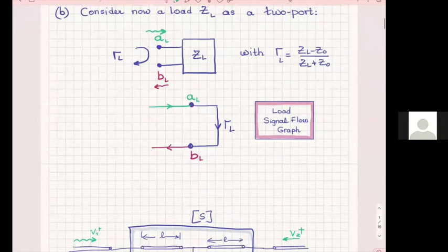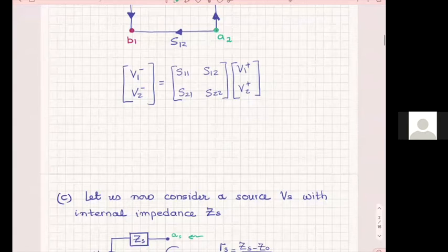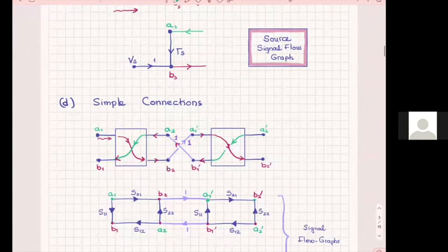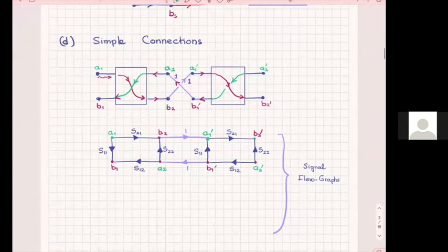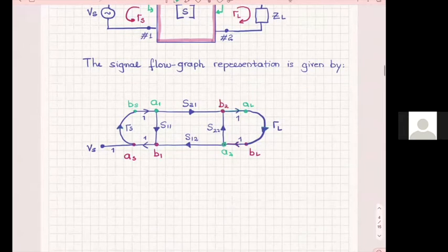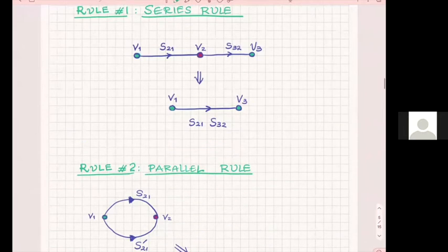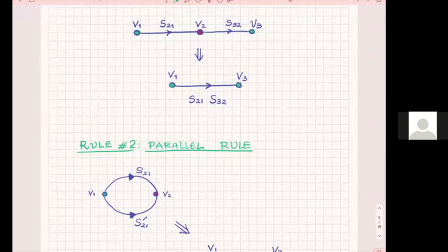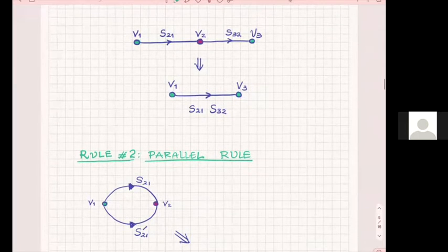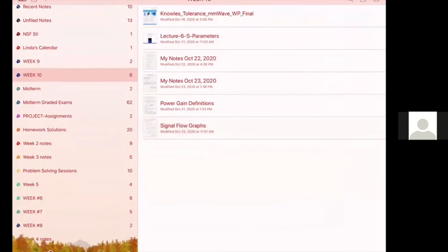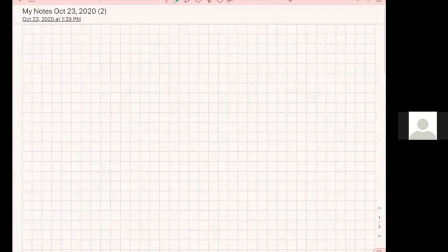Okay, well, this has to do with the microstrip implementation of the filters in the homework, and I guess it isn't really on this set of notes, but that's okay. My question was, in the homework, at some point we have to implement a series capacitor and inductor, and to do that the notes say to use, I think, a series stub. I was just wondering, in microstrip, is that possible? Is that valid to do?